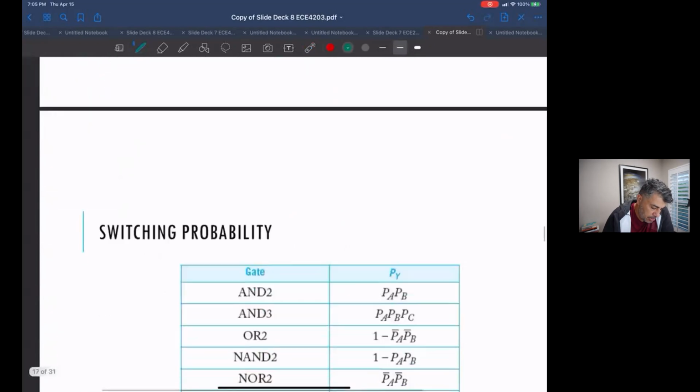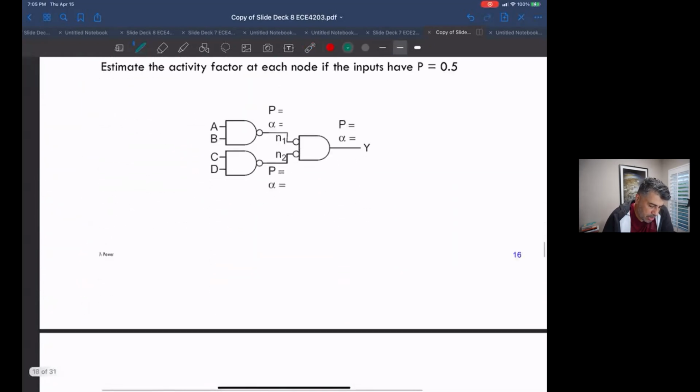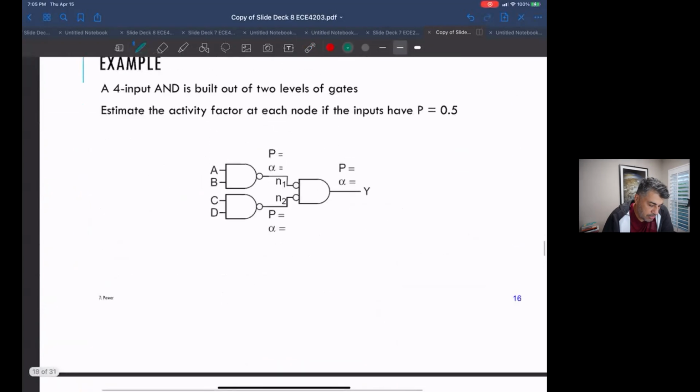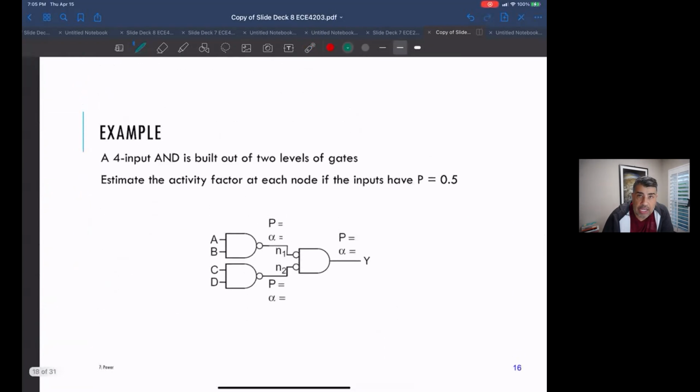Sometimes you have a memory block with a lower activity factor, and you know how often you address it because you know what your microprocessor, for example, is doing. Otherwise you just use 10% for random logic.